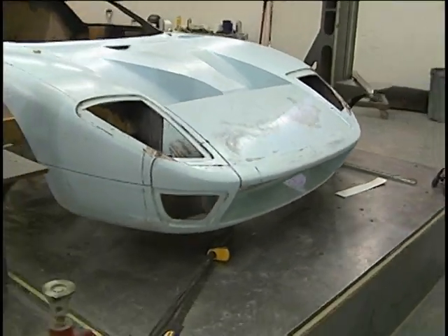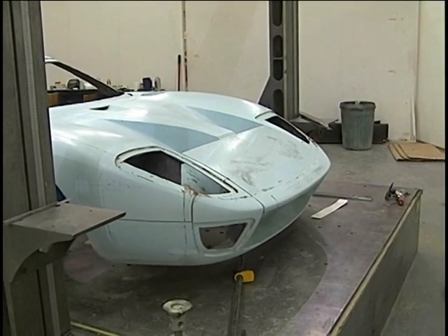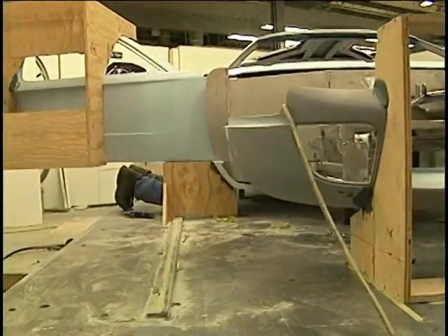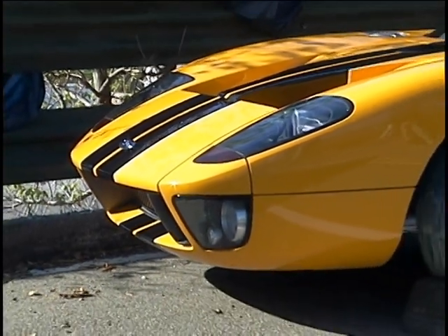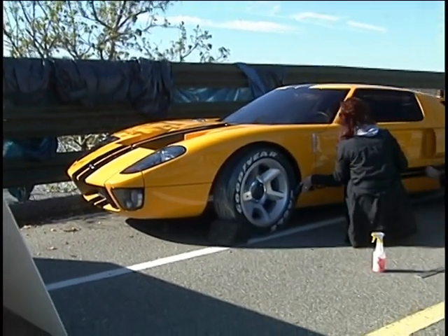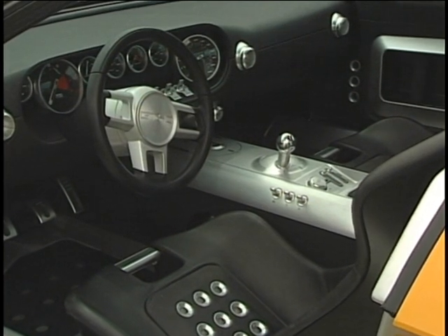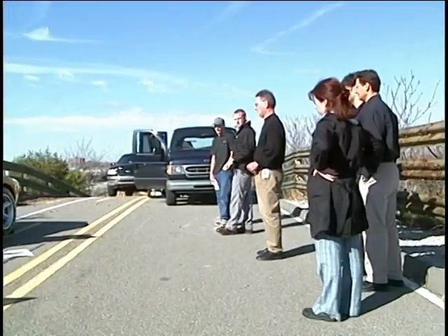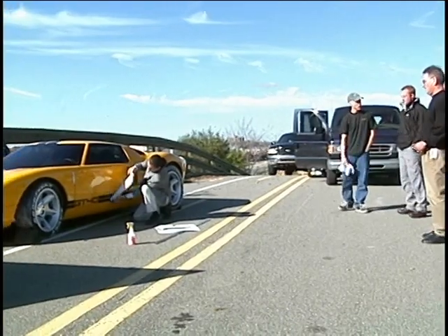Once the clay is evaluated and approved, plastic molds are made from the clay model to create a full-size fiberglass model. The fiberglass model will now be fitted to the appropriate chassis and painted. The full-size model then receives the cosmetic components such as mirrors, windows, wheels, headlamps, tail lamps, and moldings to make it complete. Some full-size models will be equipped with an interior and have functioning doors, while others are strictly exterior models. The new vehicle is now available for management reviews and photography sessions.